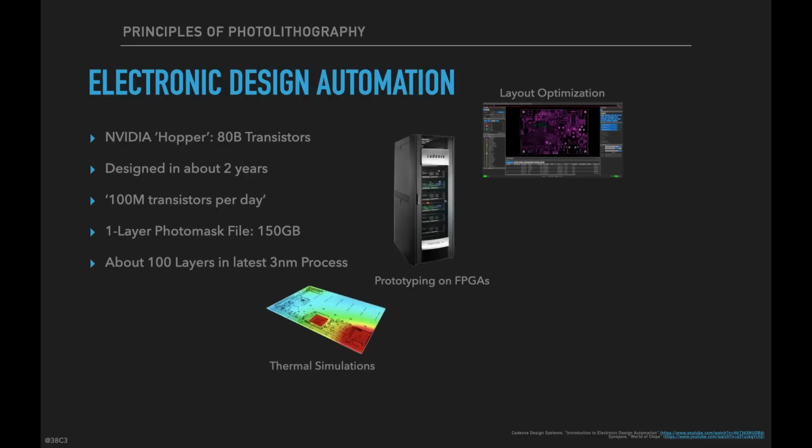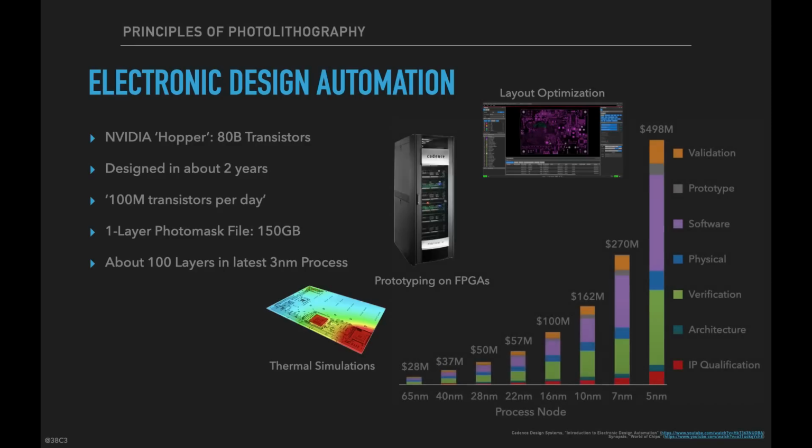And you also have to do high fidelity simulations, like thermal simulations on your chip, because you have different parts of the chip that heat up differently. And if you are at 3 nanometer process nodes, just the differential heat expansion, or thermal expansion, can already cause a problem in your overlay, right? All of these things. It's crazy what you have to think about.